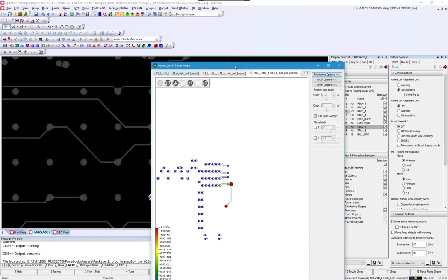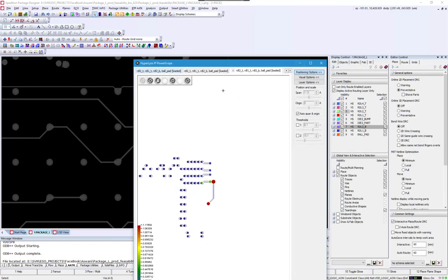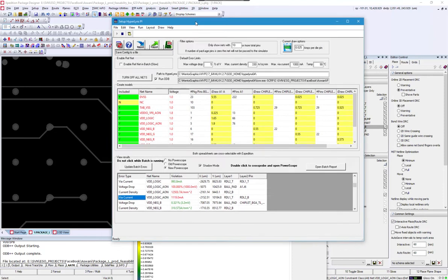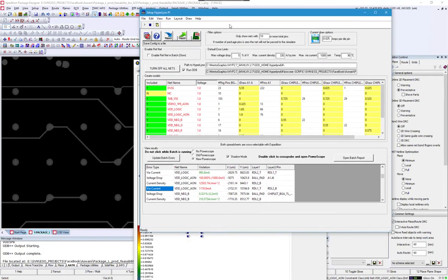So in relationship to, you know, bringing this back in, yes, we did a big rock analysis where we assumed all pins draw 25 milliamps, and we have one set of voltages and rails to test everything against. And once we do that, we can come down here and see what each of the rails did, kind of go off and poke at them. Even if they passed, it tells you what they passed with.